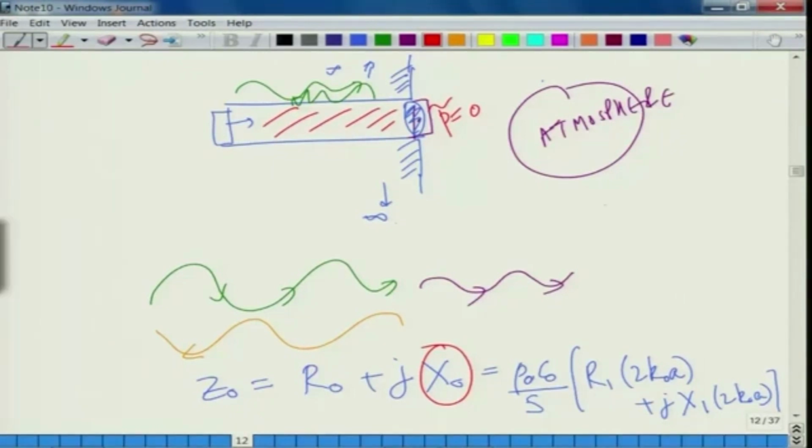So, if you do something like u squared times z dt and integrate it over a certain time, and you actually put this z naught here, the entire quantity will be non-zero because of the non-zero behavior of this. That means a certain amount of energy or acoustic power is lost per cycle, because R naught is non-zero. So, the reactance does not contribute to the power loss. It is just acoustic power being shifted into the acoustic potential energy or acoustic kinetic energy of the particles, but it is R naught that contributes to the loss.